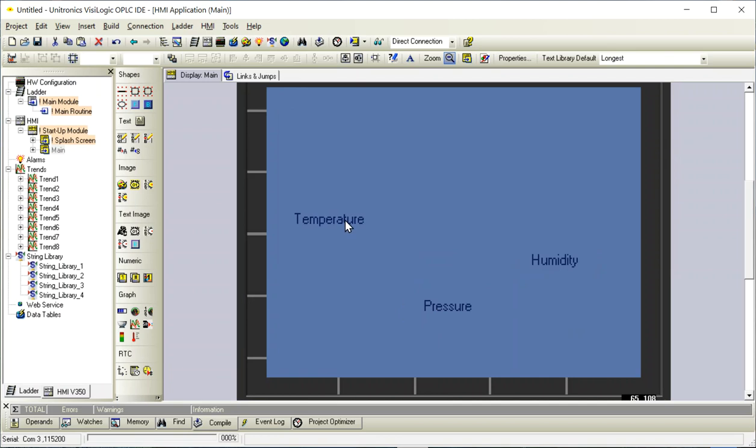Now, if I wanted to line those things up real nice and neat, that gets to be a little bit of a pain. You can put up a grid, but it doesn't snap to the grid. So what I thought I'd do is explain the two different ways that I found, then you can choose one. What I usually do is line one of these up real nice and neat where I want it, in about the right place. I select that, I hold the control key down, and I start to select multiple things at a time. That's Windows-like, right? And if I hit control again on one of them, it deselects, so you can fix any mistakes.